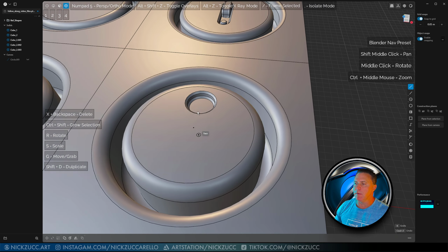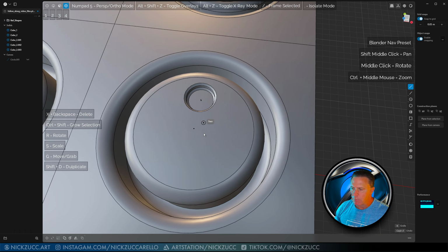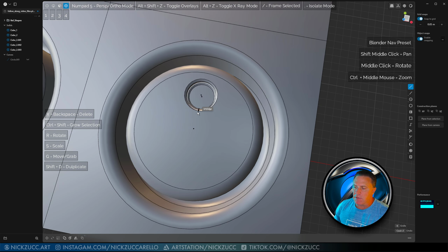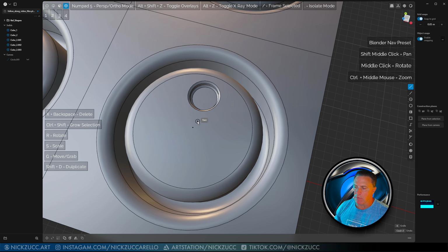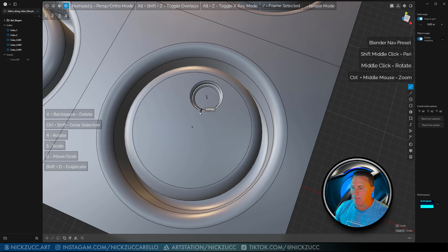I'm going to be making this feature that we have here. What we're going to do is make a straight line in here, and then we're going to use an offset of the line, and then add caps to that line. So the first thing I want to do is just make a straight line going down through here. Because I'm snapping to things, I can snap here and I can just drag out. You can see this pink line. So it's going to let me continue to snap here. If I wanted to end this, I could just click right here and end the line there.